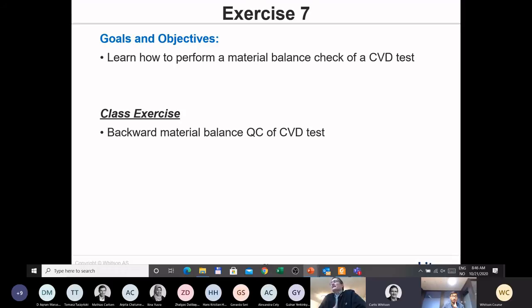So some of these other experiments, like the CCE liquid dropout curve, should be a very reliable set of data that reflects indirectly the K values, the dew point, the bubble point, and the liquid volume changing. It's an indirect reflection of the K values, but it's a very reliable set of data. If you could combine some of that type of data with some data that has reliable compositions, that would be the ideal world in a sense. But you have to make use of what's there.